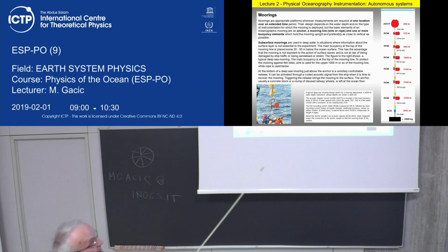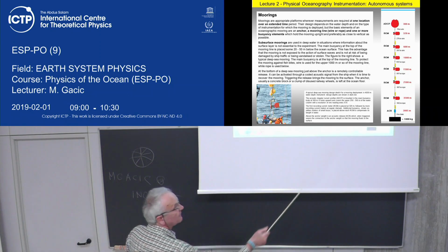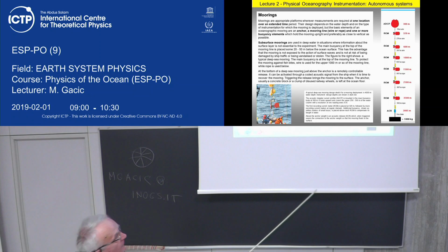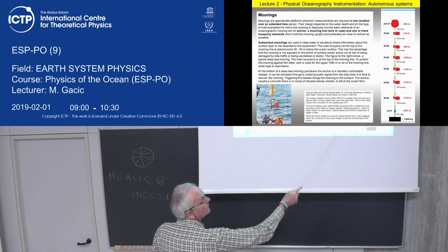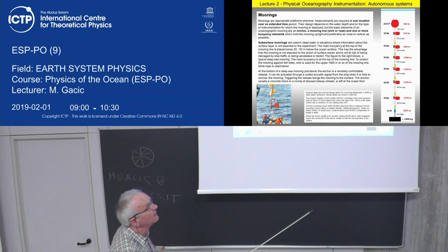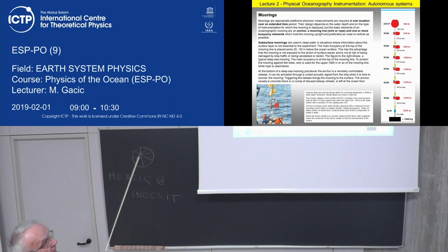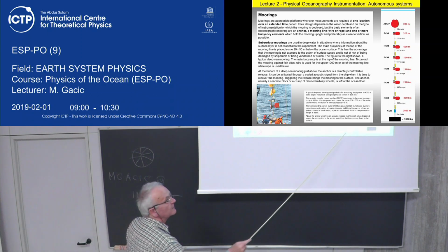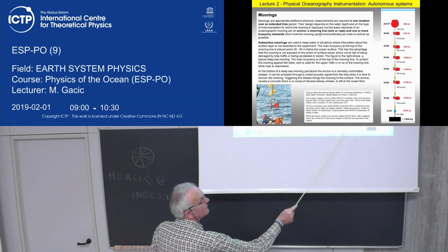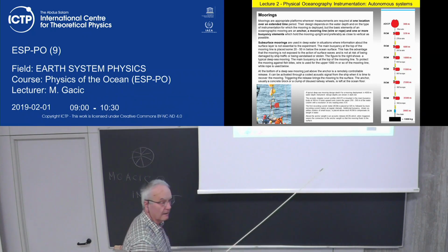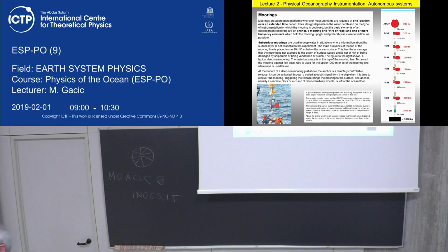And for example, in this specific structure, there are a number of recording current meters. You can see here, there is the ADCP, acoustic Doppler current profiler. There are also associated to these current meters the temperature, salinity, chlorophyll measurements, which are important, and oxygen if possible.